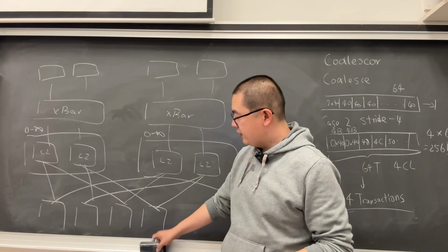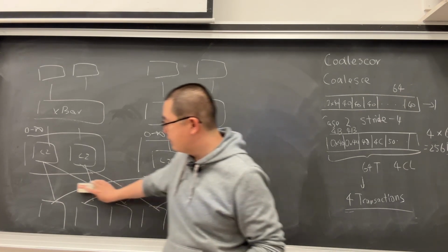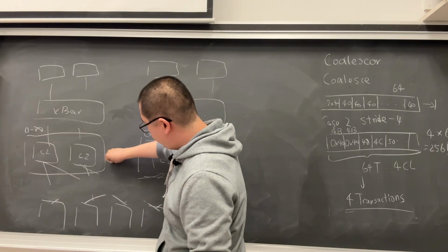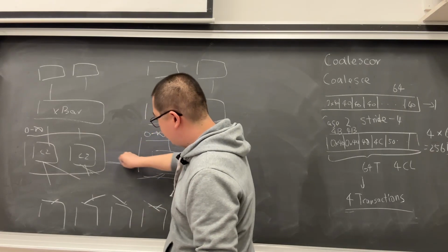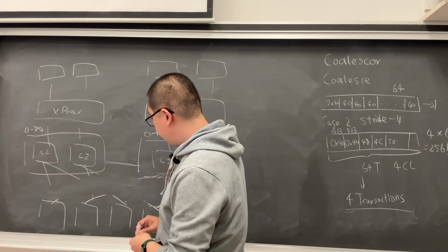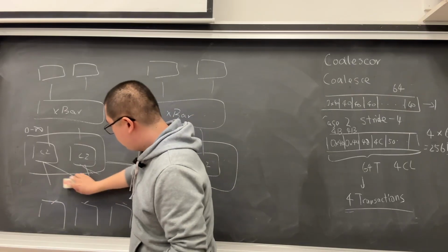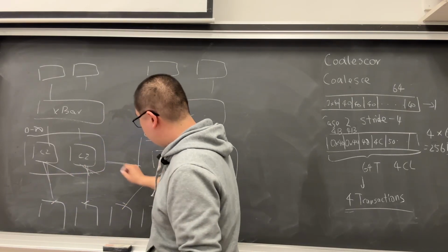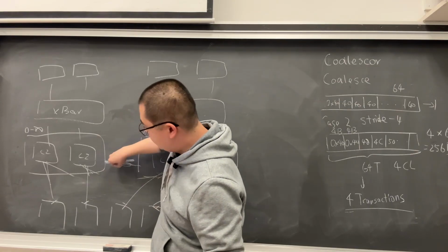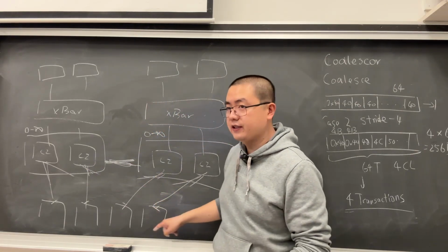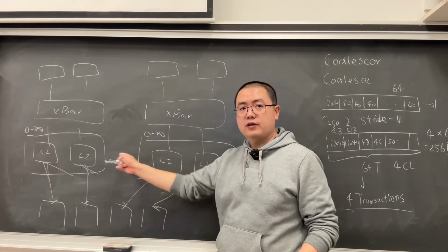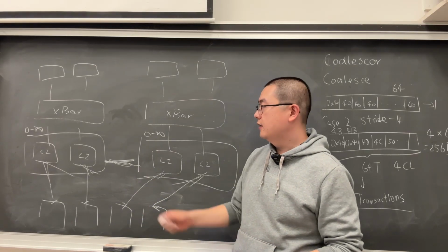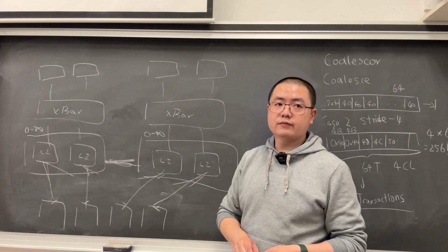They very unlikely use a crossbar here, but some sort of switch, so they probably do something like this. So there's another wire here, right? If you need to access that partition, you need to go multiple hops to reach the destination. So latency is higher in NVIDIA GPUs.